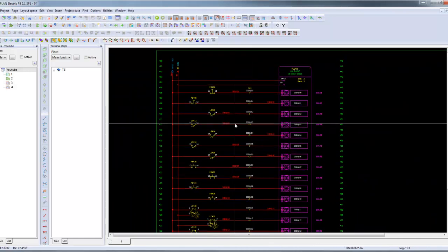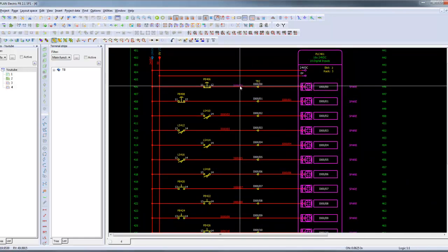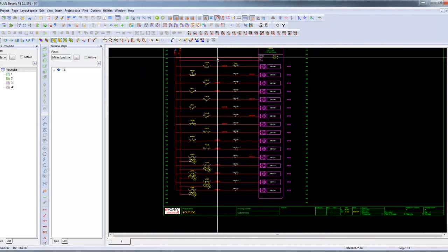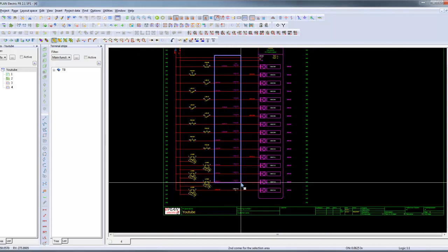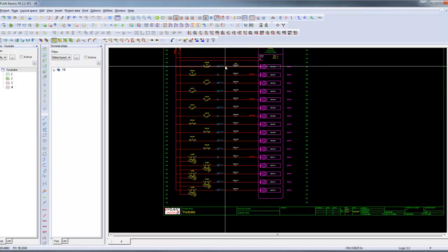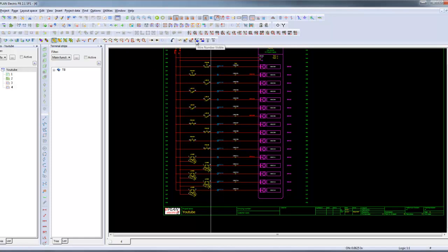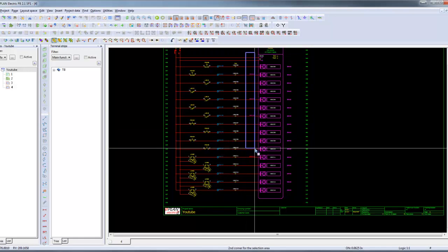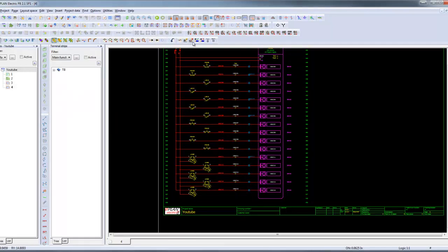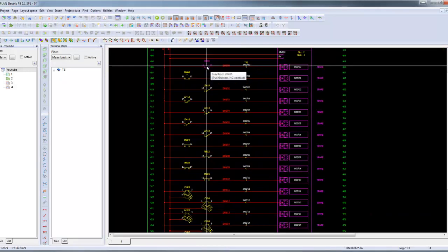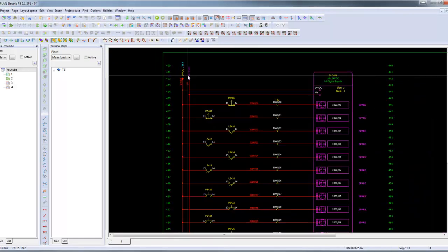Now I have these wire numbers that came through a little bit random and off-centered. So I'm going to grab all these guys, and I made a little toolbar here which aligns them vertically. Click right there. There we go. All these guys here I want the wire numbers to be visible, and on this side I got a little toolbar to make all my wires invisible. It's basically toggling between visible on or visible off. That just makes it look a little bit more aesthetic, and that's it.